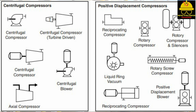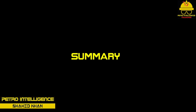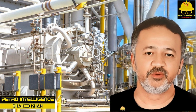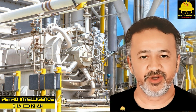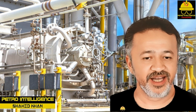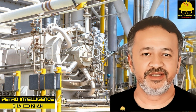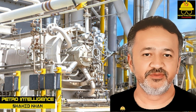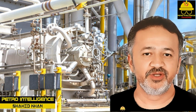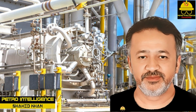Compressor symbols. Each type of compressor can be represented by a symbol. This picture illustrates compressor symbols. Compressors differ from pumps in that pumps move liquids and compressors move gases. Compressors are used to transfer granular powders and small plastic pellets from place to place, to establish feed gas process pressures, to provide clean, dry air for instruments and control devices, and to compress gases such as light hydrocarbons, nitrogen, hydrogen, carbon dioxide, and chlorine.